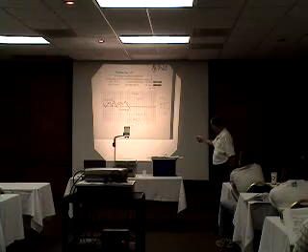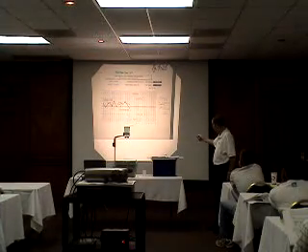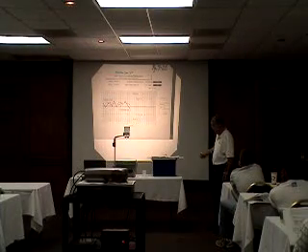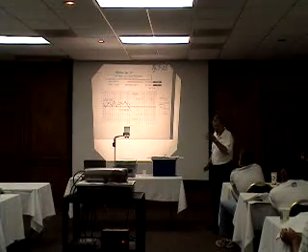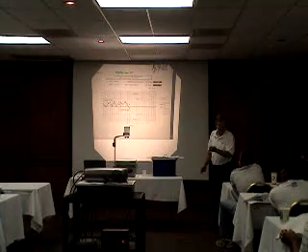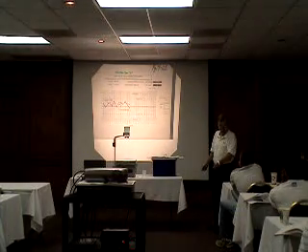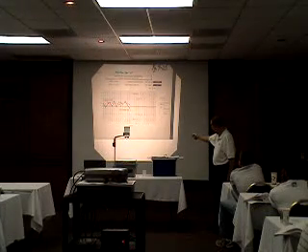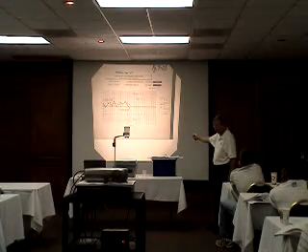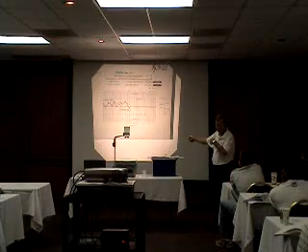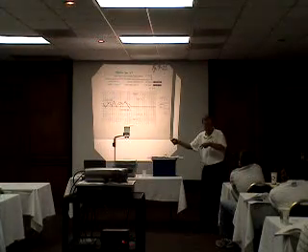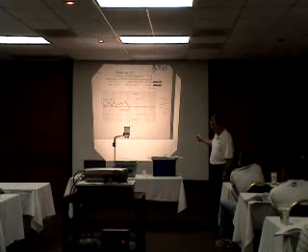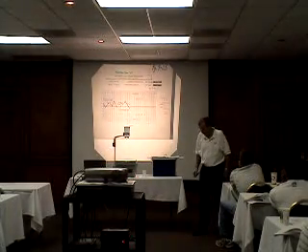I run test number 5, and I plotted it. It ran 4.0. Connect with a black line there. I averaged test 5, 4, 3, and 2, and I drop 1. The last 4, and I plot that as my next red one and connect it with a solid red line. And I just continue on like that. I plot the individual, and I average the last 4. Only the last 4, and that's my moving average line.